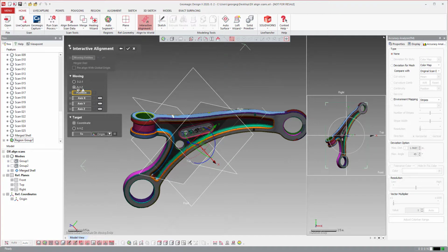The XYZ method is actually interesting because you have your position and your directions broken out into separate dialogs here. Position is where the 0 is going to be. So how do I put 0 right there? And then the directions are how I square up the different planes and axes with the widget, the XYZ 0, the origin, right?